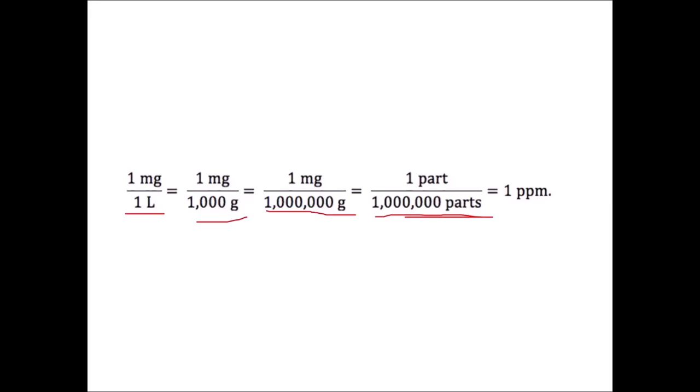In this expression, the milligrams in the numerator represent the mass of solids, while the mass in the denominator represents the mass of water. For this reason, the concentration can be expressed either as milligram per liter or as parts per million, ppm. So, concentration can be written as mass per volume or mass per mass of water. This equivalence is valid for water because its density is approximately 1 kilogram per liter.